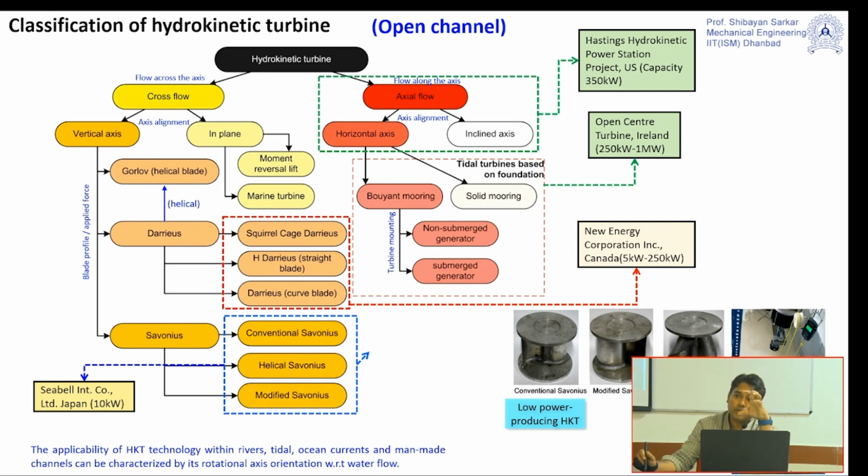So in this manner, we try to find out the best position, around which we would like to run our turbine. What should be the best speed, and how much will be the maximum power output we can achieve through the turbine. This is the exercise we generally perform before manufacturing a particular turbine and installing it at a site, because manufacturing a turbine is difficult.